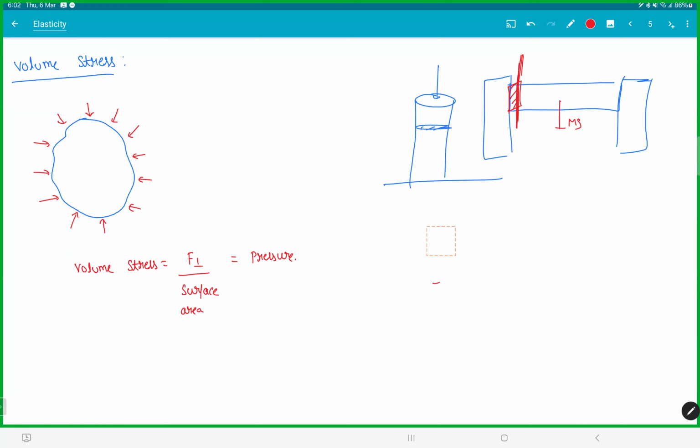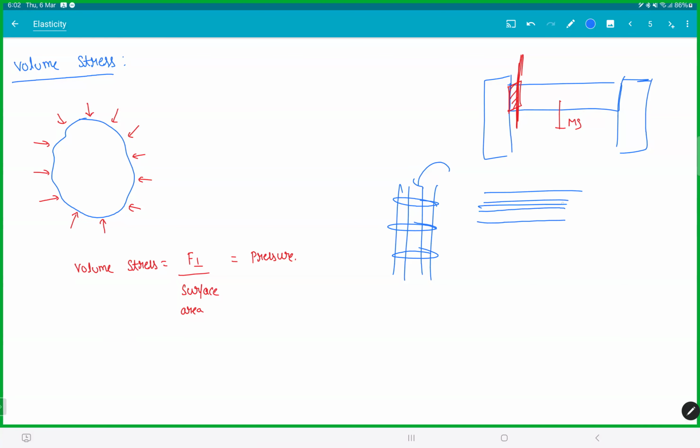That is the reason next time when they build any pillars, observe this thing. They first construct, they put some metal rods, they cover this with metal wiring, and then they pour concrete inside. But if you take the construction of a beam, you will observe they use double the steel, double the metal coverings, and then they pour concrete. Because concrete has a problem. Concrete, when you're compressing, is as strong as steel. But the moment you take a concrete block and try to apply force in terms of stretching, concrete will tear into pieces. Concrete is very strong in compression, very bad in elongation.